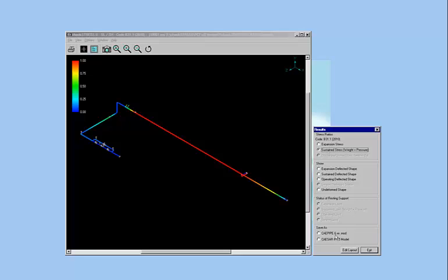One, you can simply send this file over as a kpipe file or a CAESAR II file here for further stress analysis by the stress engineer. Or, since you already have access to the GA drawings, you might as well play around a little bit by adding a few supports and then see if it makes a difference to your line. There are two ways you can do this. You can go back to AutoCAD and make the changes there, re-extract the PCF file, come back here, and run it through checkSTRESS, and it will tell you whether it's red or blue.